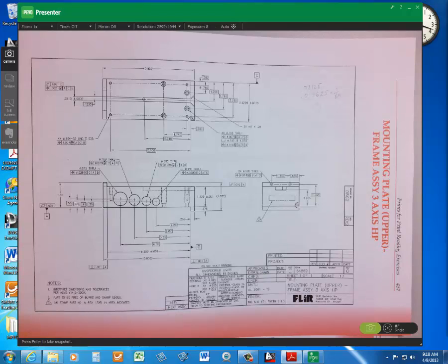Now, occasionally we might have a counterbore and put a standard old hex head down in there. But if you do that, the counterbore has to be very large, because you have to allow room for the socket to fit in there and have room to play. If it's very deep, then it's got to be pretty large so that you can wiggle and get it in position and get it off, in case it gets stuck.